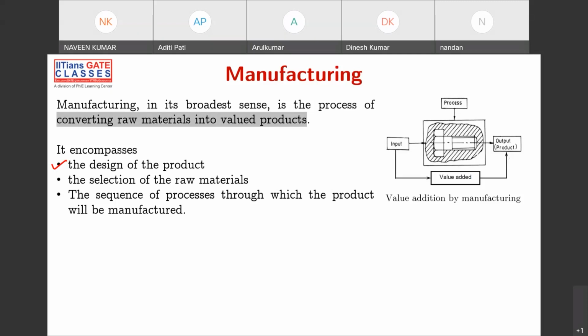But you take material. Which material do you want to use? That is where material selection comes in. You want to make a plastic chair, or an iron chair, or a wooden chair? What do you want to make? Once your material is fixed, you keep your calculations ready. Young's modulus is fixed, shear modulus is fixed, all properties are fixed. Using these properties, you size the material. What should be the length of the leg? What should be the base of the leg? And how much weight it has to take? All these things you keep, and you design it.